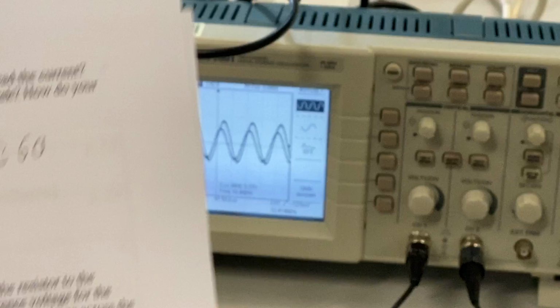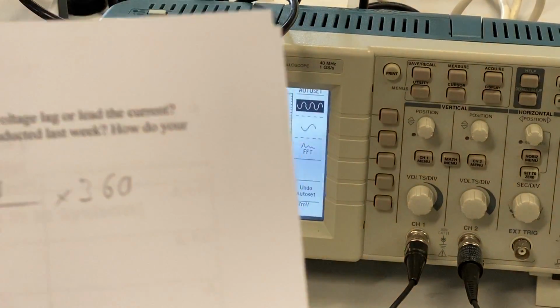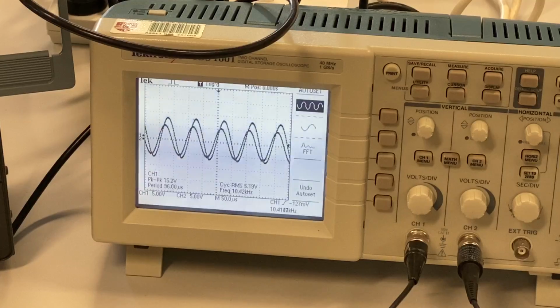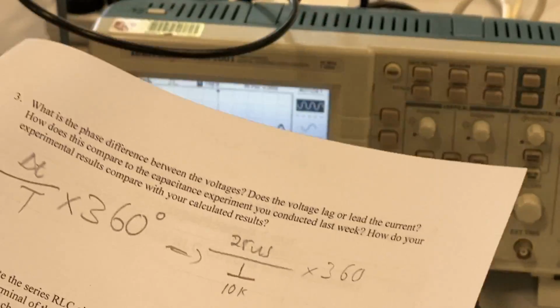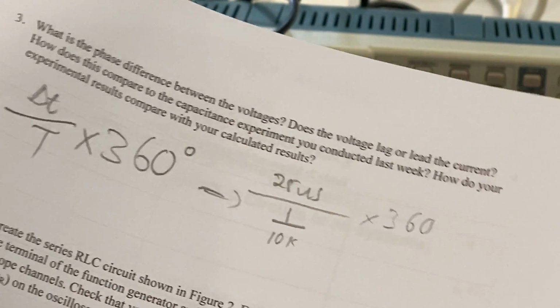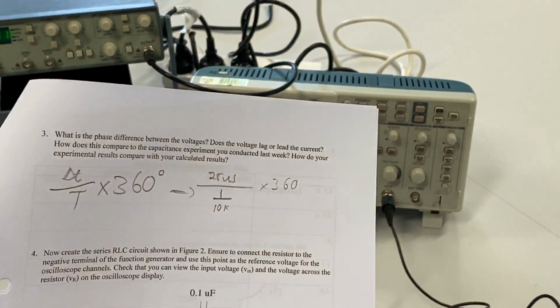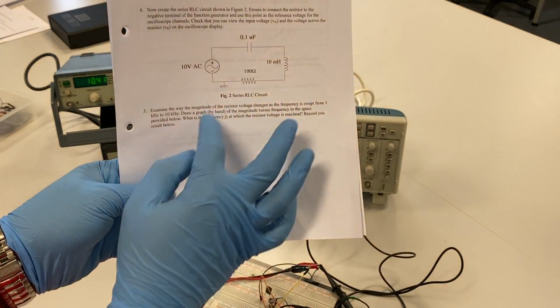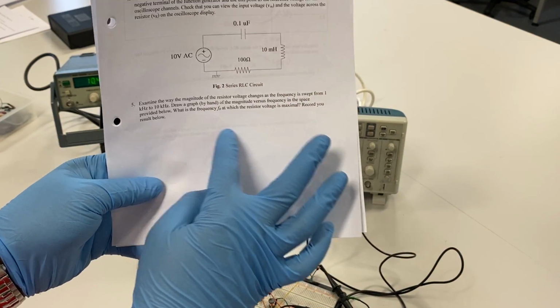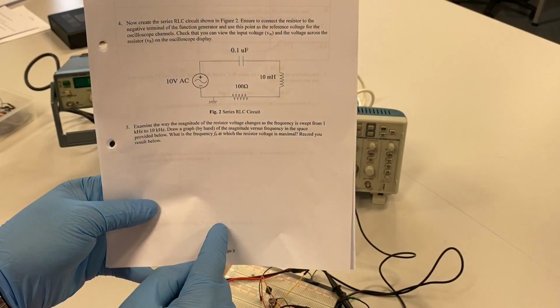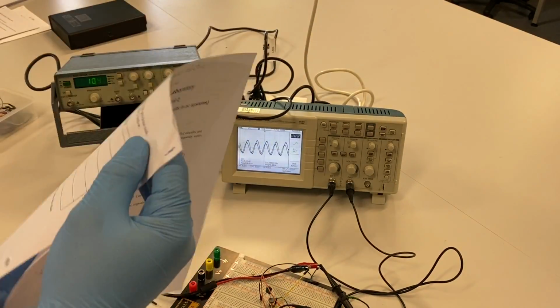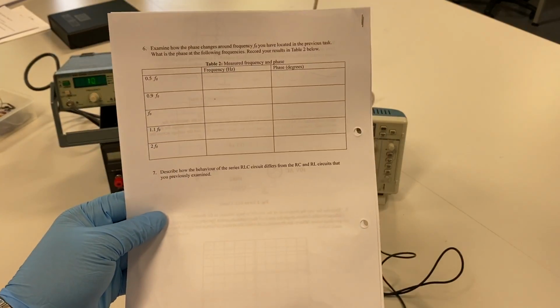So once you have this frequency F0, at which you find the resistor voltage, which is the voltage across the resistor, to be maximum, you find maximum peak to peak of channel 2 at that point. Because once you draw a graph, you see at which frequency it becomes maximum. Because you're going to plot frequency versus resistor voltage, what you will have will be a curve. At that curve, you see a turning point where it becomes maximum. You record that relative frequency to F0. Then using that F0, you complete the last section of our lab, right?